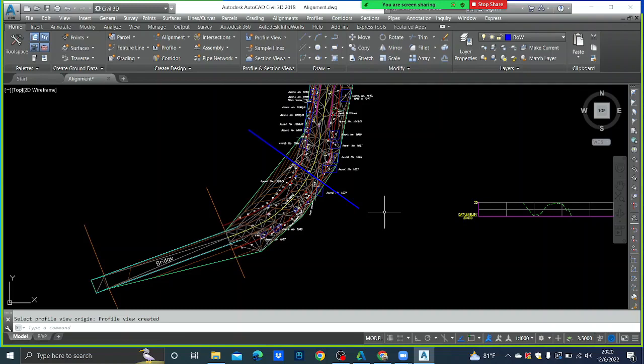Sometimes, if you want to have accurate levels, you have to get the points using the leveling instruments, right? Sometimes we don't do that in the design stage. We are just giving our profile using these levels because that is pretty enough for the tendering purposes.